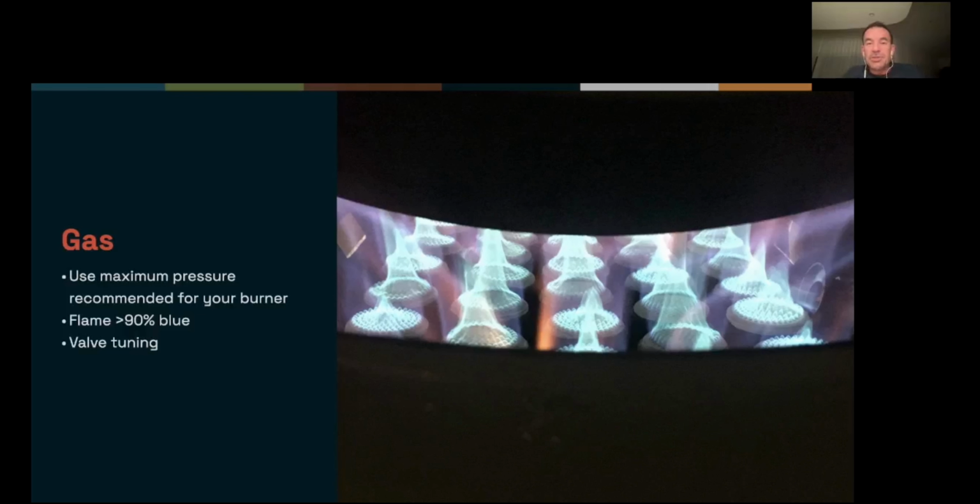When it comes to the gas, your gas valve should have a sticker on it that says something like operating pressure 10 to 50 millibar. And if you have, for instance, 30 millibar of incoming pressure, and you were to ring up your machine's manufacturer and say, hey, it says 10 to 50, I have 30, is that okay? They will always say yes, because it will work.